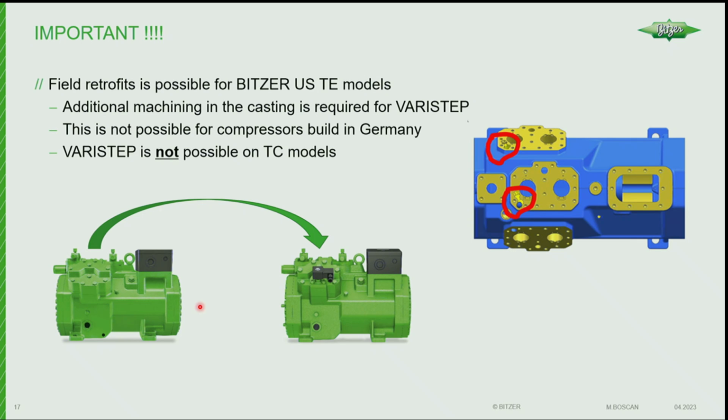Also, what happens in the field with a VFD? It blows up, or there's an issue on a Friday. What happens? They put it in bypass, and then you forget to come back or whatever else. Because VFDs are complicated. I mean, we sell a lot of VFDs as well. There's a lot of parameters, and they can get complicated. And in many cases, the VFD ends up being bypassed at some point, and then the end user loses the benefit of the VFD. This mechanical unloading is very common. People, I think, are more comfortable with it, and it's easier. So there's benefits to both.